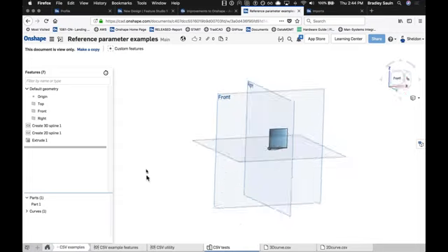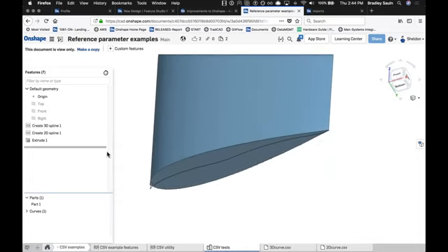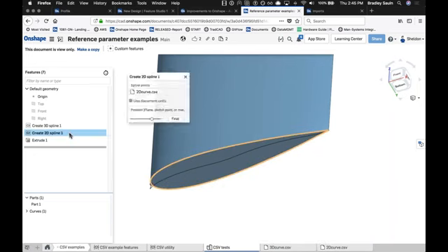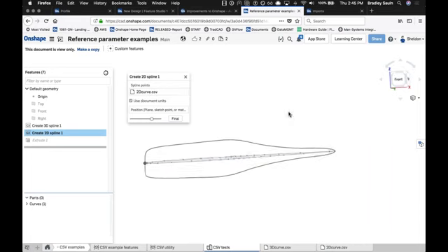In this case, with the CSV example, what it's showing off is just what we talked about in terms of when you're writing the code. We have 2 separate CSV files that can be utilized here. In the past, you would probably have to create 2 separate features using that import function to reference each of these independently. Again, it's just a static selection choice. With this create 2D spline option, you can actually go in and choose which of the files you're pointing to and grab that data. And so you're using the same feature across the board here, which is pretty nice.